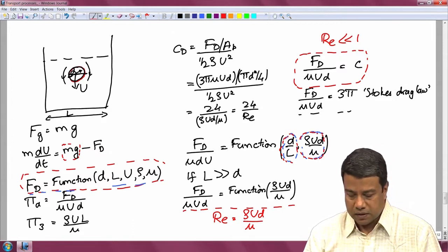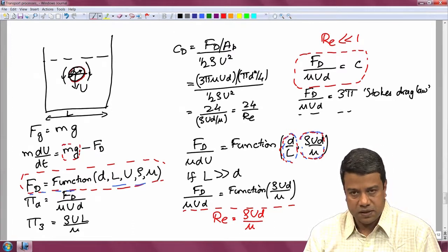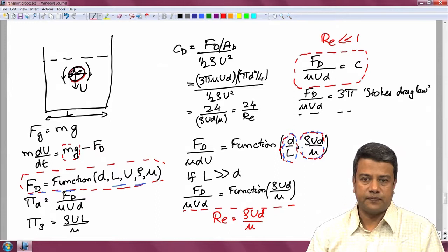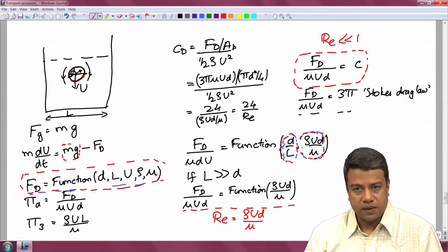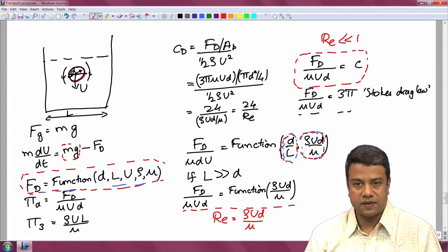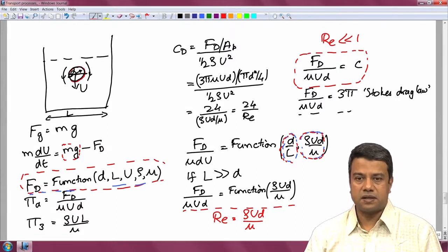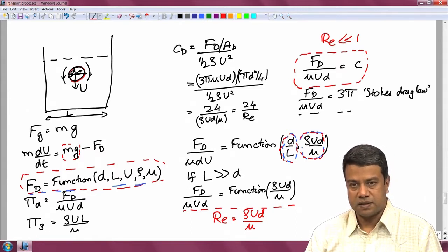When fluid inertia is much larger than fluid viscosity, the situation is a little more complicated. You might simplistically think that fluid viscosity can be neglected altogether. However, in that case, there is effectively no friction at the surface, and therefore there will be no drag force. Fluid inertia is the equivalent of convection of momentum. Fluid viscosity is the equivalent of diffusion of momentum.